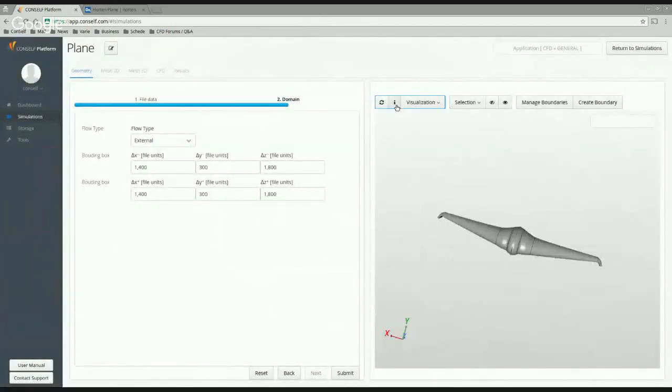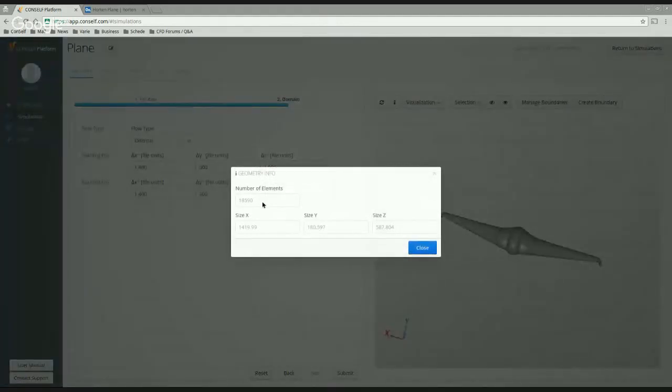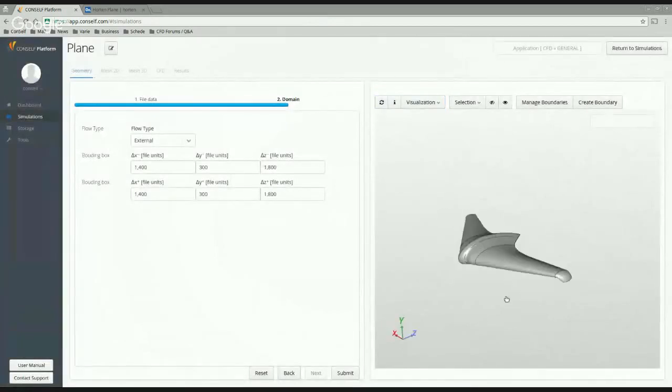And the y, so top and bottom, I'm leaving almost 2 times the sides, and in the z direction, I'm leaving about 3 times it. This is because the main interaction between the fluid and the surface will be directed along the z-axis. So this is a good choice for our bounding box.